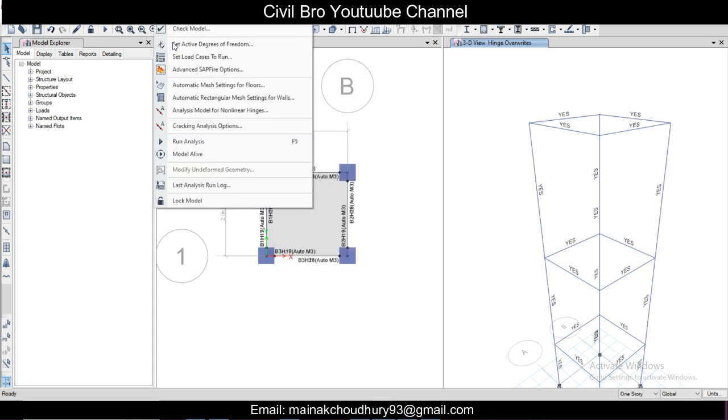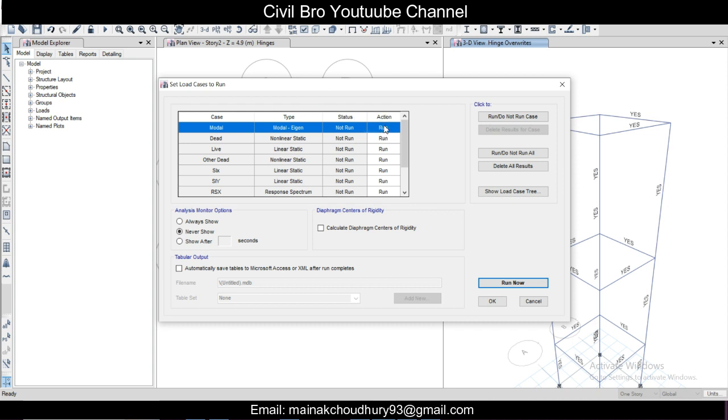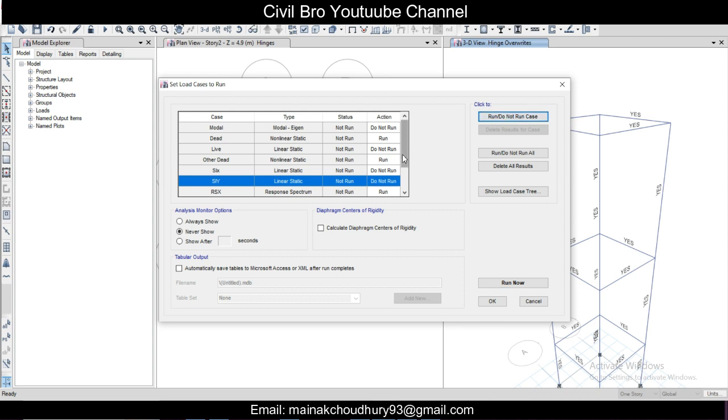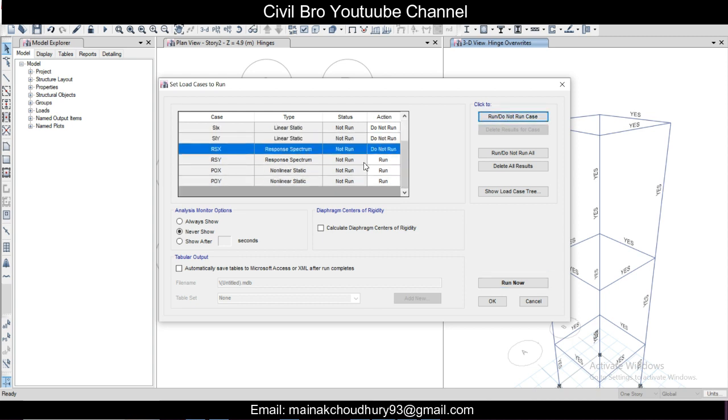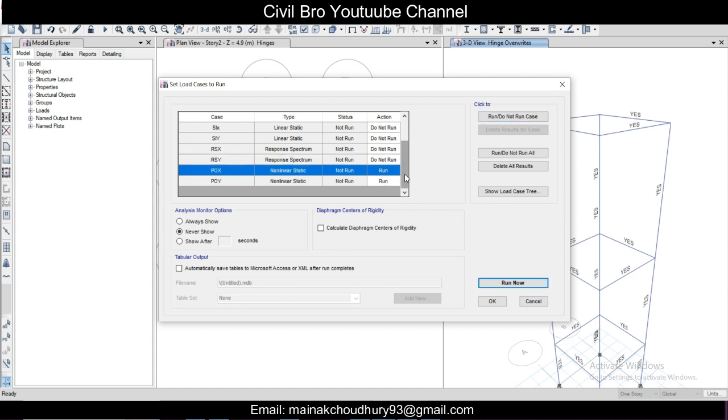Then we'll go to analyze, and we will go to set load cases to run. For this one, do not run. Dead you need to run, since all the non-linear will run. Other dead, non-linear will run this. SLX do not run. SLY do not run. Response spectra also do not run now. This also do not run. PQX and PQY you need to run. So this you need to do, and just click on OK first.